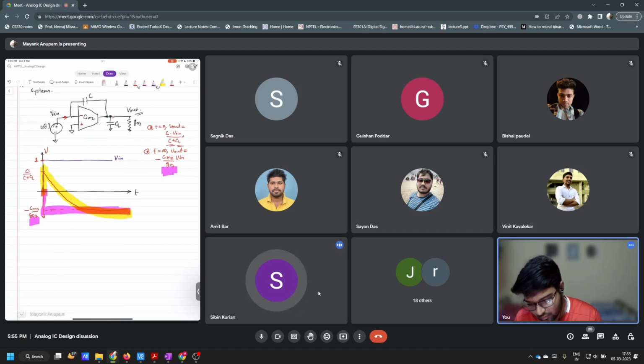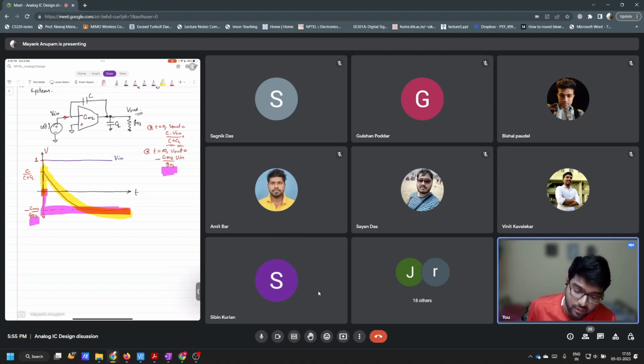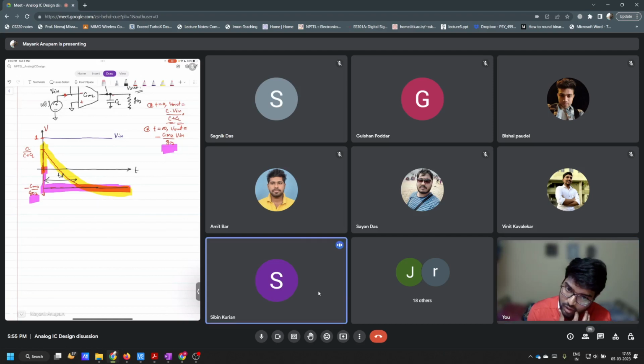So it's because it's taking that opposite direction that the delay is coming. Yeah, exactly. It's a huge blunder that this 0 is introducing. The 0 is directly pushing the system in the opposite direction to where it should have headed. That is why you can clearly see it in the time domain response. Ideally, the ideal response was like this, but it is taking forever to settle down. So this is basically a delay, isn't it? And this delay is coming because of the 0. Correct? Understood, sir.